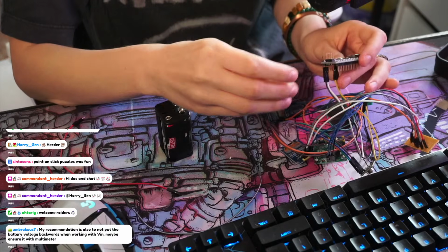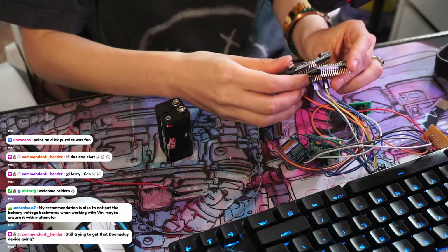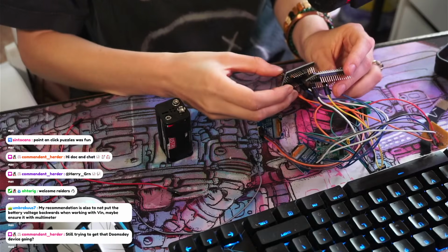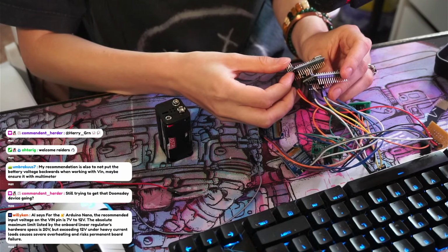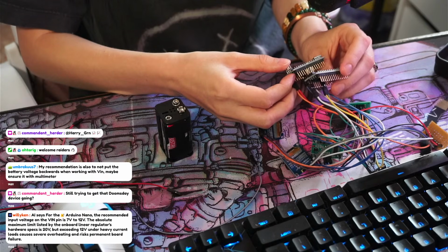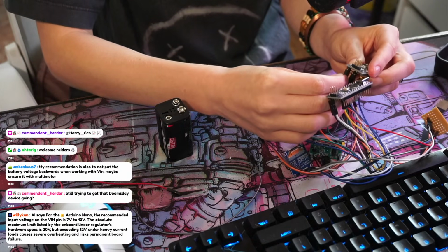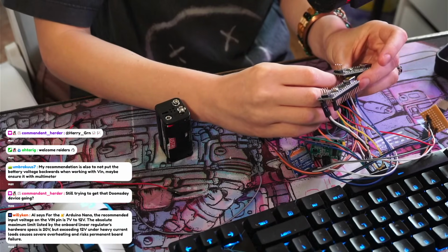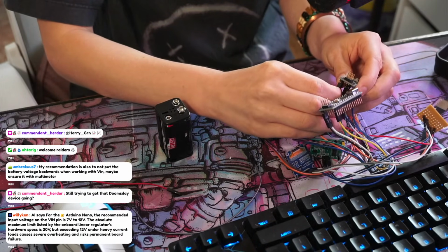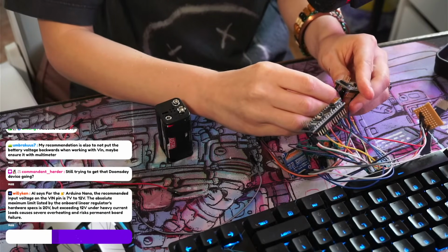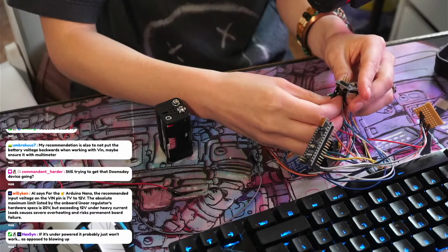So I use VIN. I use the VIN pin in the Nanos, both of them already. Why? Shouldn't I be using the 5 volts? Can I just unplug them and put them in the 5 volts? I already used the ground though, that's a concern. Do I have another ground? I do, I have 2 grounds. Although we can make a common ground actually. I can just connect it back to this one and solder it.